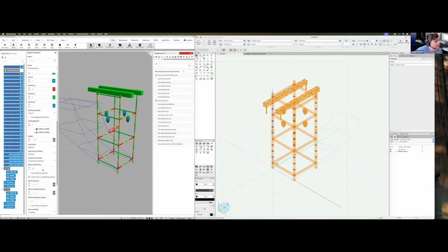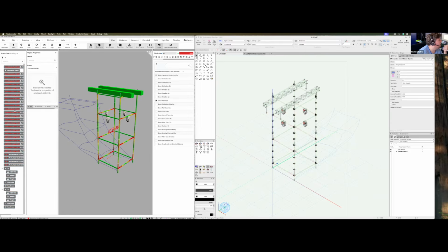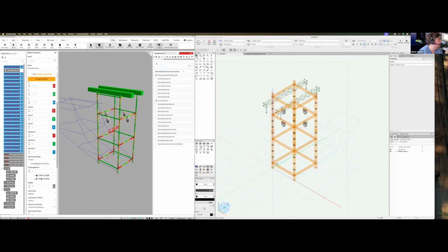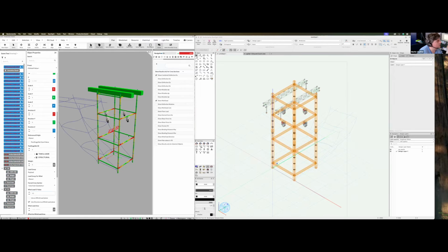Normally this is a value bigger than 1 because there is push and drag on these cross sections, but the value always depends. The value 1.8, which is the default, is basically the worst case scenario, so that is normally a conservative approach. What we know right now is, and I quickly use select same name for this and select all of these and all of these, I can tell them it is 1.2 because it's a steel tube. You see now it's gone down a little bit.